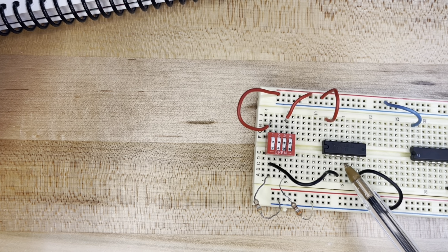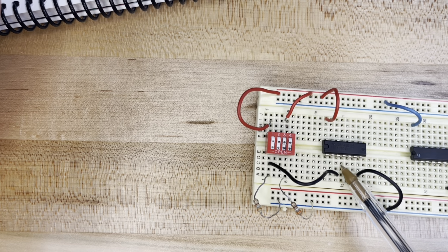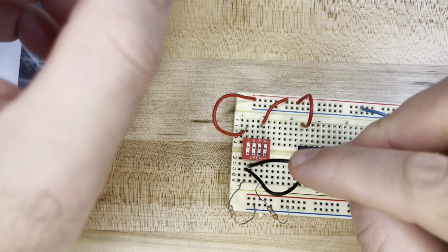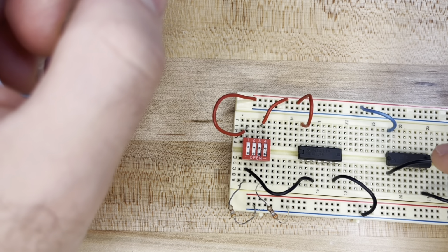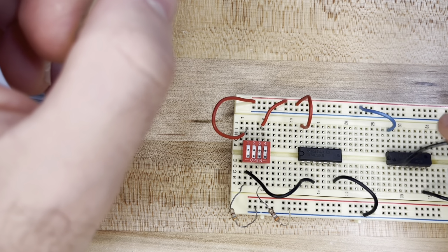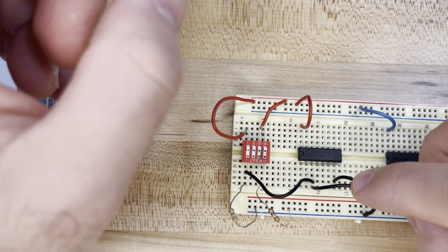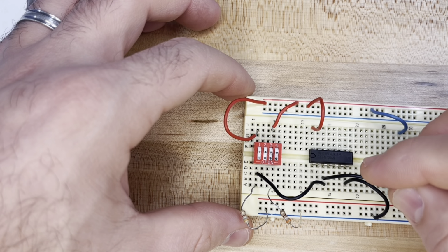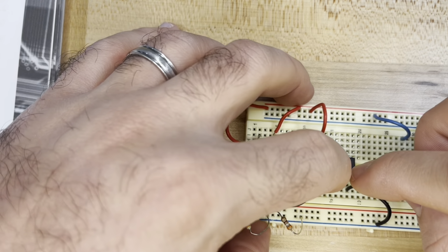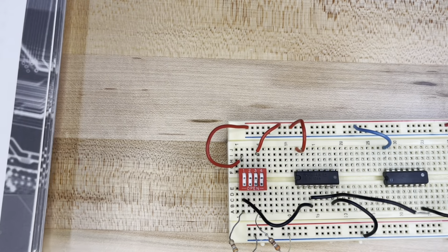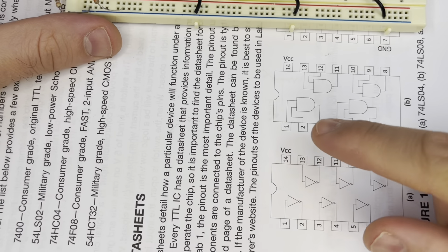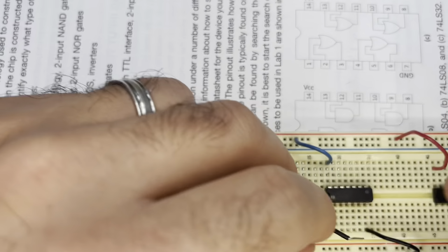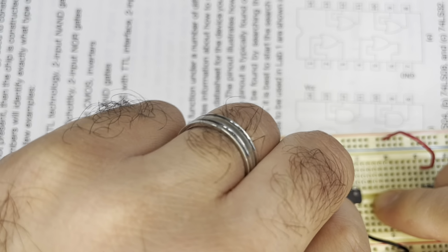Now which this goes to pin number 3, I have pin number 4 if I want to read X naught, which is the output. Now I'm gonna continue plugging X. So rather than taking X from the switch to the second gate, which is the AND gate, I'm gonna take it from the same column, hence we know that the entire column is connected. So I'm gonna take it from this point, and it's gonna stay X, and then decide where is the inputs for the next gate. For this one, I'm gonna use the first one, so pin number 1 and pin number 2 is the inputs. So I'm gonna stick it to pin number 1.